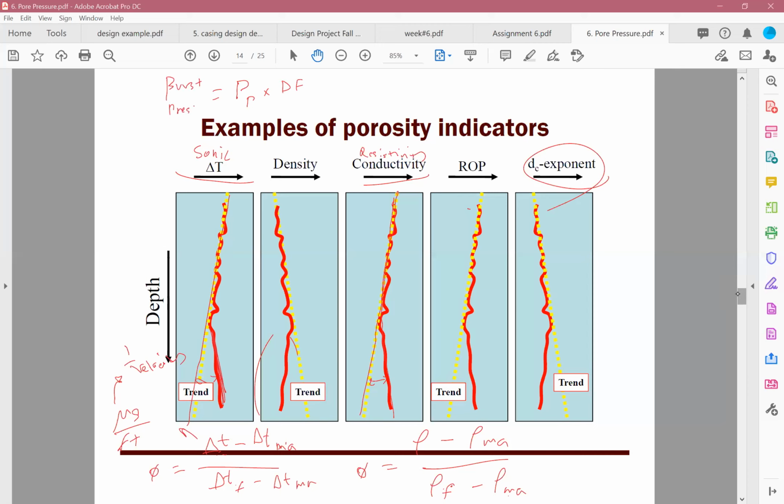So you would need your pore pressure when you design for the burst requirement, right? So therefore, pore pressure with depths is important for you because you would need to have that for your burst design criteria. And that's the only place. Yeah, we don't use it for tension. We don't use it for collapse. For collapse, we use the mud density.